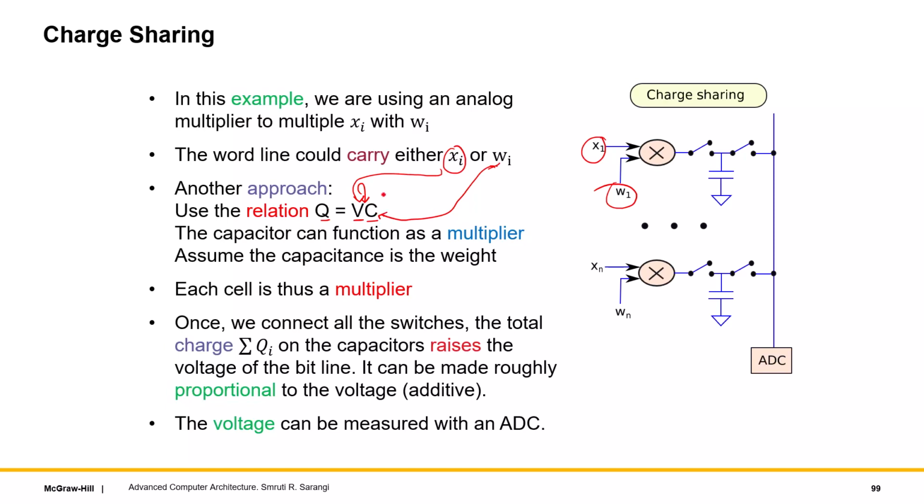This is where quantizing it to a few levels or using a binary CNN will turn out to be helpful. In any case, once this charge is generated, it is stored on these capacitors, which are essentially in parallel. So capacitors in parallel, the capacitance basically adds up. That is the equation. What we are doing is charge sharing, in the sense this will deposit some charge here, some charge here, some charge here. So charge is going to get shared.